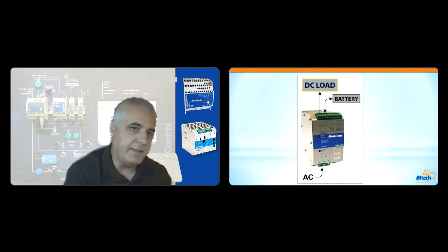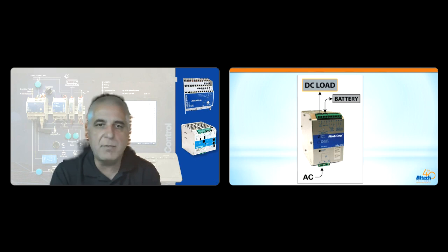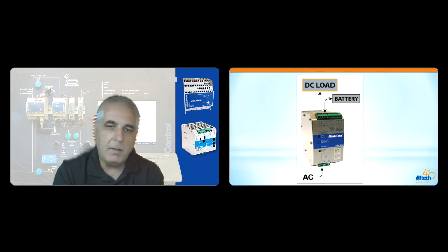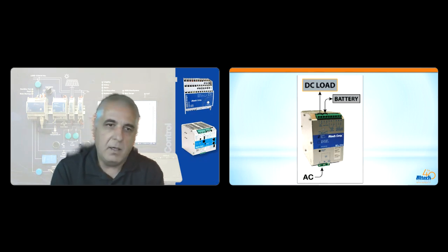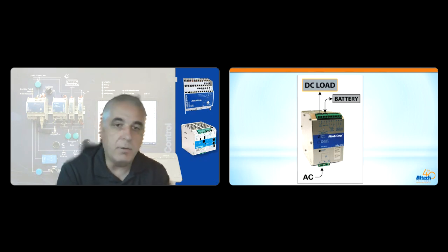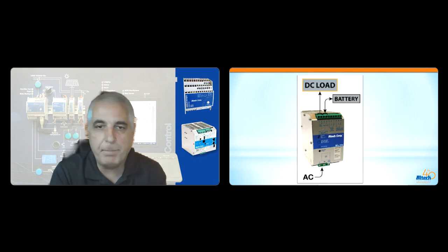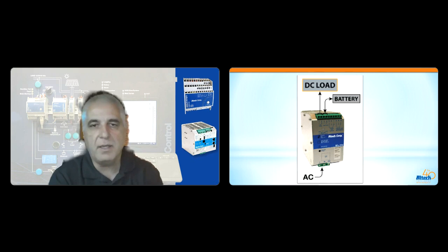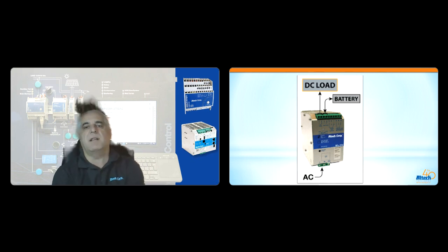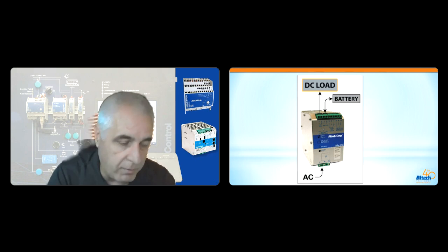These units have an adjustable maximum battery charging current. Basically, you can adjust the charging current between 10% and 100%. Our DC UPS backup system has a battery start function. This function allows users to restart the system with battery power when the main AC power is off.